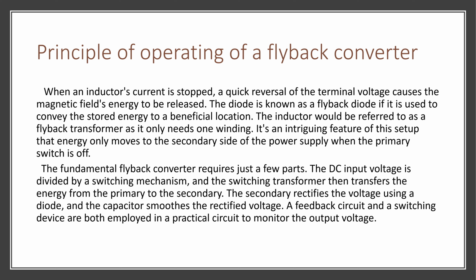The principle of operating a flyback converter. When an inductor's current is stopped, a quick reversal of the terminal voltage causes the magnetic field's energy to be released. The diode is known as a flyback diode if it is used to convey the stored energy to a beneficial location. The inductor would be referred to as a flyback transformer as it only needs one winding.